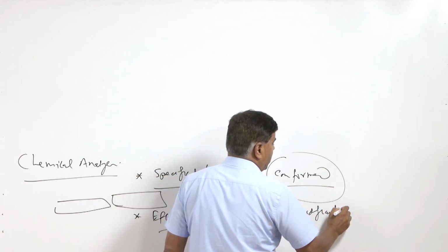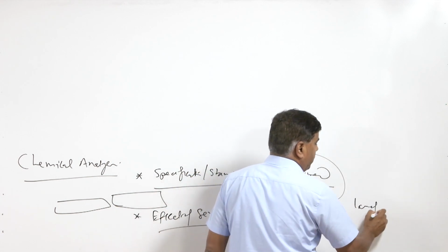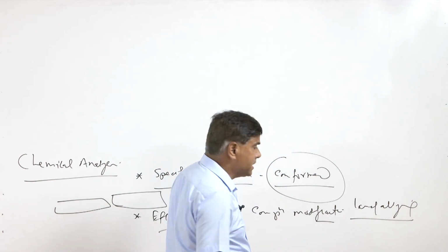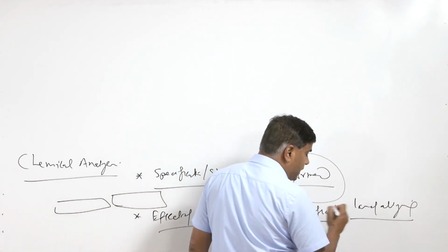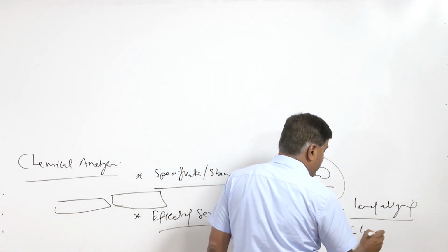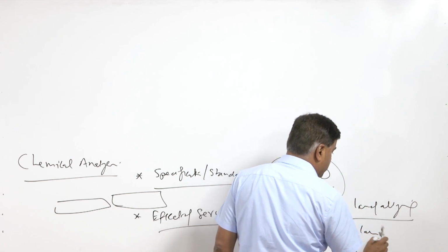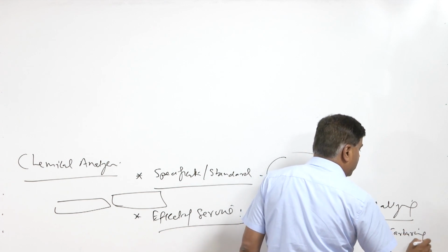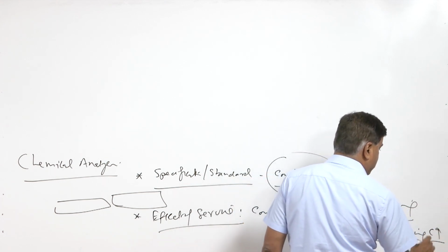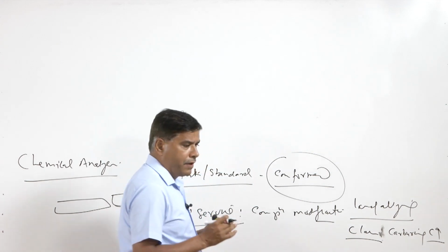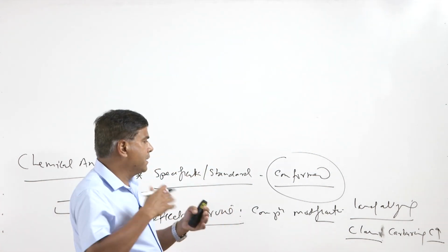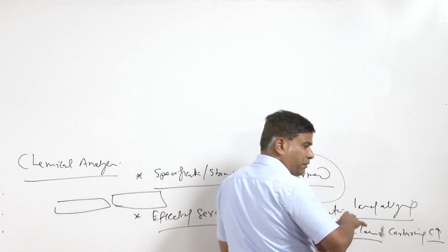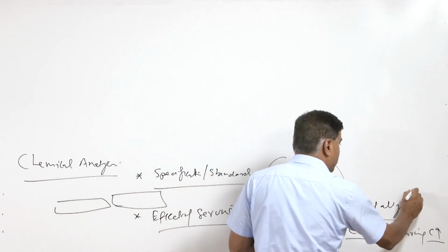This can be in the form of loss of alloying elements, which we commonly see in terms of decarburization, where loss of carbon takes place, or carburization, where the carbon content is increased. Likewise, exposure at a high temperature for a prolonged period can also lead to the loss of other alloying elements from the component.